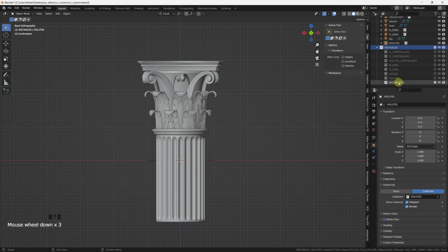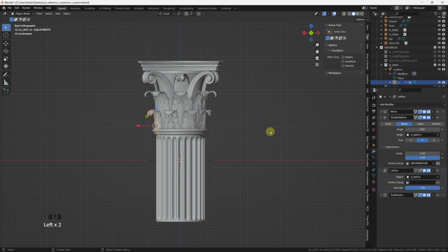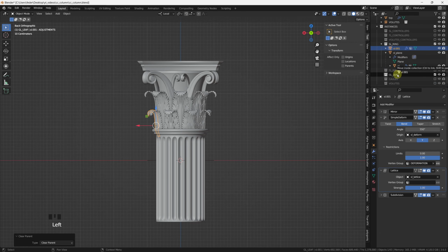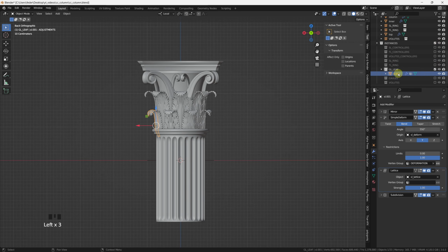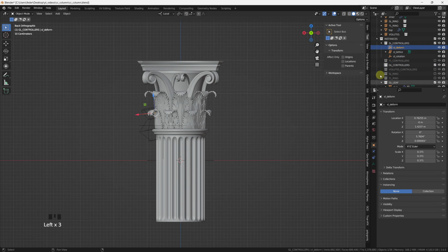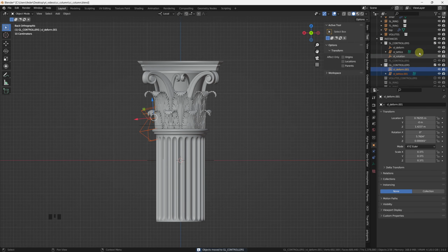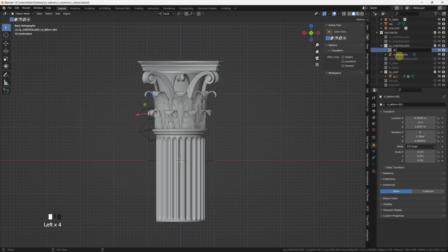Moving on to the additional leaves sprouting from the Caules, I created a new collection and called it gl_leaf. Then I took my short leaf, duplicated it, and I removed the original parent-child relationship with old p. And of course, also in this case, I want this to have its own controllers. So I created a new sub-collection and call it gl_controllers. And then once again, I borrowed the deform and lattice controllers from the SL leaf, and I duplicated them and moved them into the newly created sub-collection.